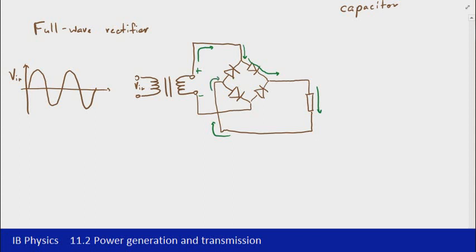Now because this one was already reverse biased, we know that current can't now flow up, because then it'd be coming back up to this point, and that just doesn't work. We don't have a decrease in potential across that diode, and so current then has to flow down this diode and then back around to the supply. So that's on the positive half cycle, so this half cycle of the input.